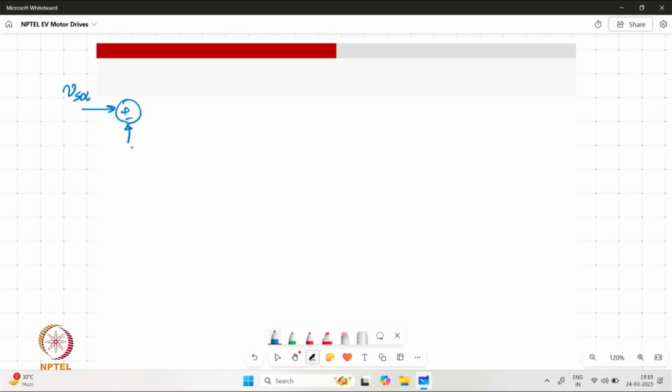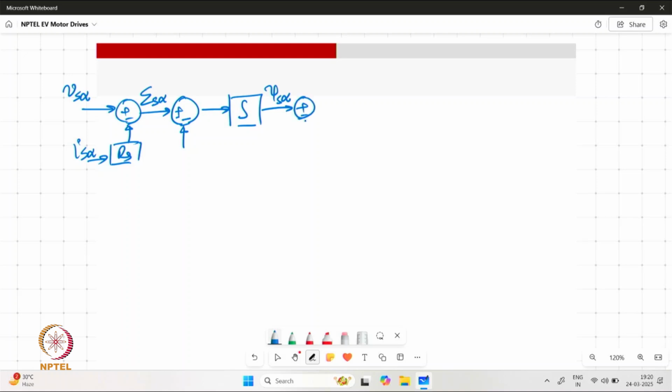So eventually we are computing our error voltage which requires a correction for stopping the DC drift and other issues. And then we need to have the same process. We have the integrator which is generating the psi s alpha. The rest of the model stands as it is.